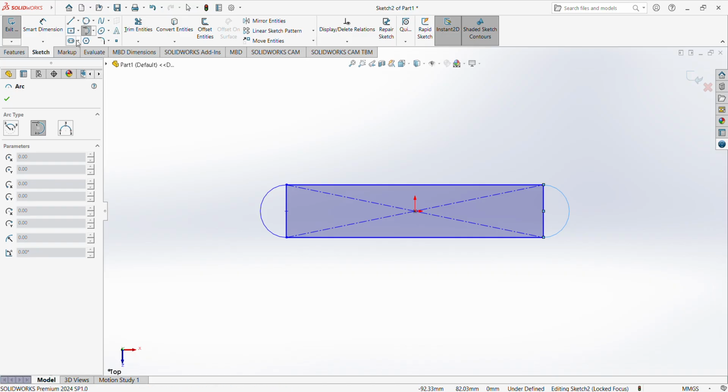So the next thing is your slot tool. The one that I majorly use is the straight slot tool. For all these tools, looking at the shapes they produce on the drawing, like on the top right, you can easily tell what they are used for. So these are the slot tools. You can have a simple straight slot tool, or a center point straight slot tool, where you click a center and then the other end. Then these ones are for when you have arced slots. Just depending on what you want to achieve.